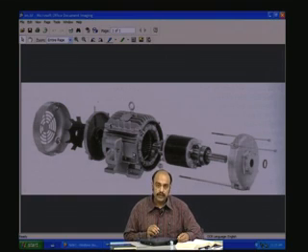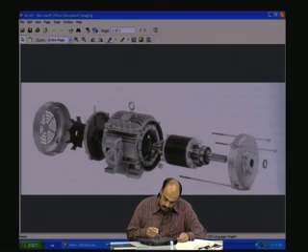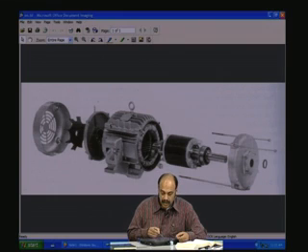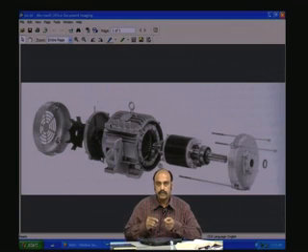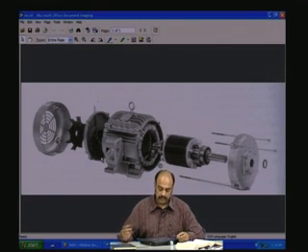This is a squirrel cage induction motor. Now all these windings here are clubbed together and brought out as terminal points, A phase, B phase, C phase, and also the neutral. You saw that we connected all the neutrals together for the other end of the coils of the various phases.